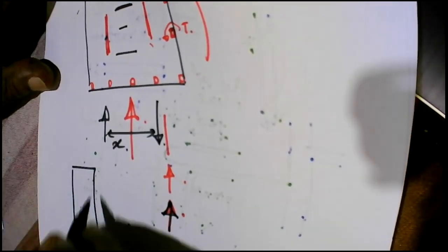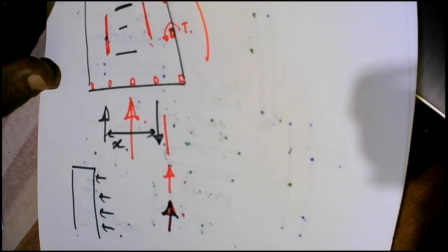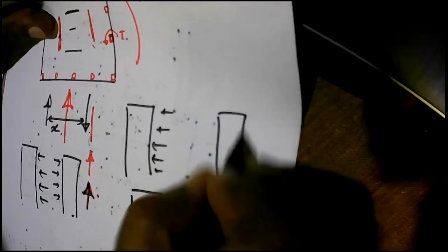Again, the shear wall will also not be subject to torsion because the shear wall resists the torsional effect in the form of in-plane loads. So one shear wall will be subjected to a load like this. The other shear wall will be subjected to loads like this. So the net effect is, we have the shear wall subjected to lateral load and the same shear wall subjected to lateral load due to torsional effect, and the shear wall on the other side, same, but that shear wall will be subjected to load in the other direction.